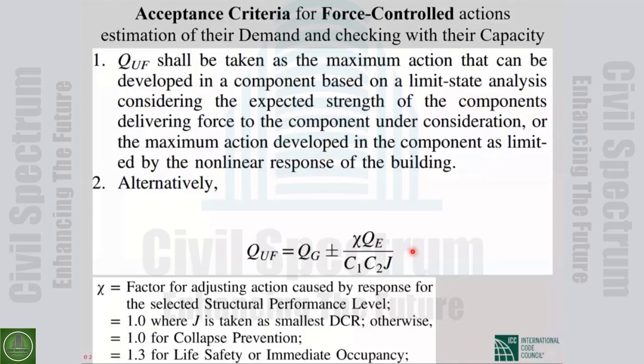We say that the amount of lateral load that we impose on the building is too much. We impose that to have the building reach the same displacement as in reality, but that is to check the deformation control parameters. For force control parameters, we want a good estimation of force distribution. There is no need for C1, C2 for the force estimation. There is another point too.